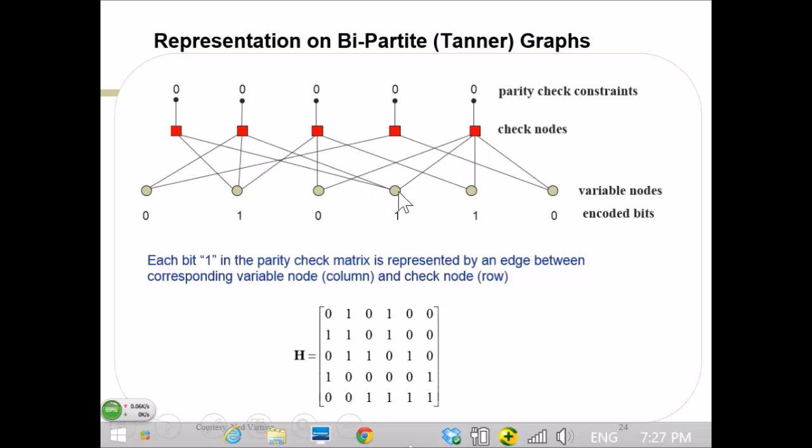So there is a 1 and 1, both added together. That's a GF2 addition, a simple XOR operation for the binary LDPC. So it becomes a 0. Similarly for this parity check, you have 0, 1 and 1, so again all 3 add up to 0. Essentially when you are transmitting, you made sure that the bits are such that all the parity check constraints are satisfied as 0.